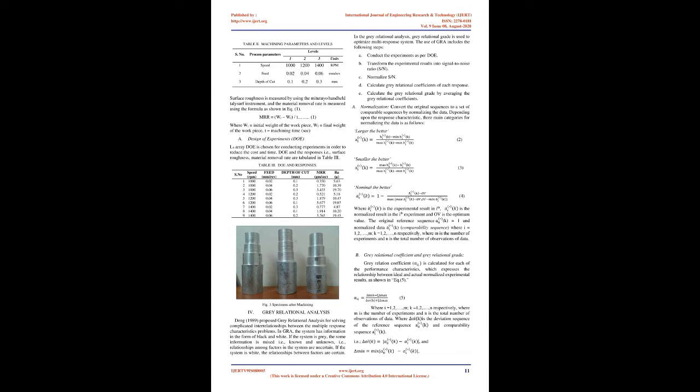And then, the specimen was placed on the viewing stage of the inverted metallurgical microscope and the microstructure was examined with the monochromatic light source, and photographs of the microstructure were captured at a magnification of 500x. Fig 2 depicts the microstructure of Al/SiC MMC, to ensure the distribution of SiC particles in the melt.